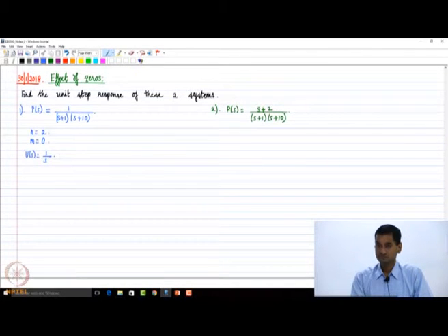If we're looking at the transfer function, how can you decide the order of the equation? Maybe it is a third degree equation, or m is 1 degree. How can you decide? You look at the numerator polynomial and the denominator polynomial. The denominator polynomial is a second order polynomial here. Of course, we are not considering what are called pole zero cancellations. We'll come to that shortly. We are assuming that a pole and a zero are not at the same location. With that assumption, we can see that the denominator polynomial is of order 2, so n is going to be 2.